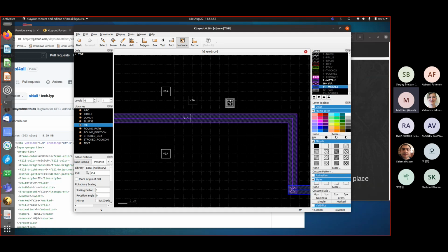And that is a matter of hierarchy settings, because the cells form a level of hierarchy. So I have a parent cell and a child cell now. I have a top cell and a child cell. The child cell is the cell used inside a cell. That's the naming convention which is typically used in this context. I have basically a 2-level hierarchy this way. So I have a top cell and I have a bottom cell.